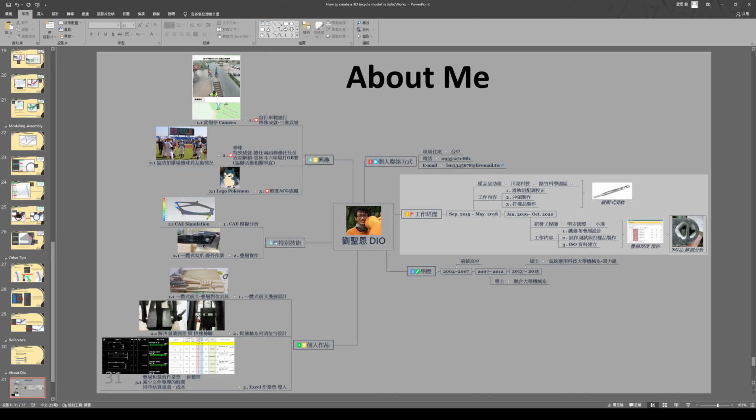Number one, I assisted in designing an alignment feature that helps to sidestep the carbon fiber product easily. Number two, I designed a checking gauge that is quicker and more accurate than the old one. Number three, I changed the way the layout instruction is expressed by using Excel. It's easy to manage products, material, and quantity.